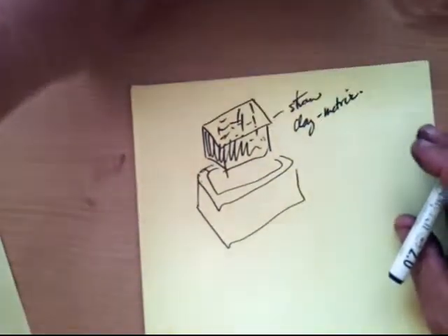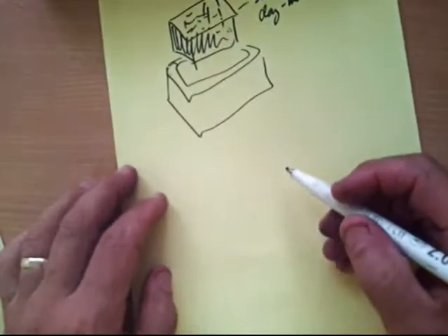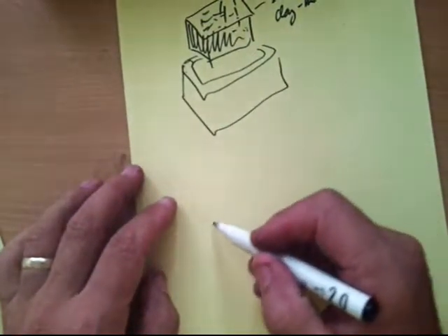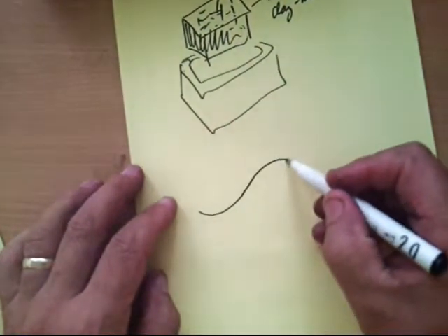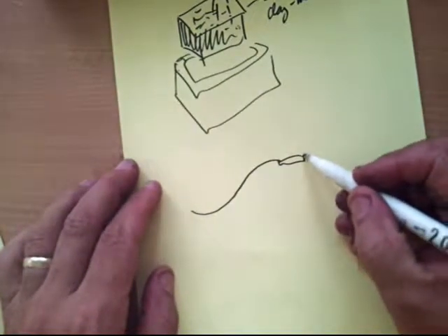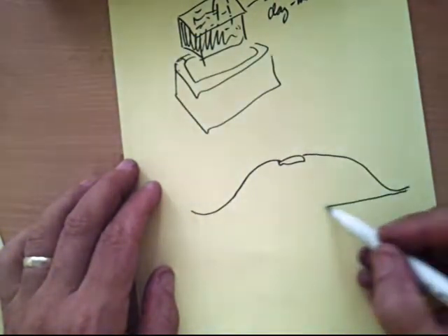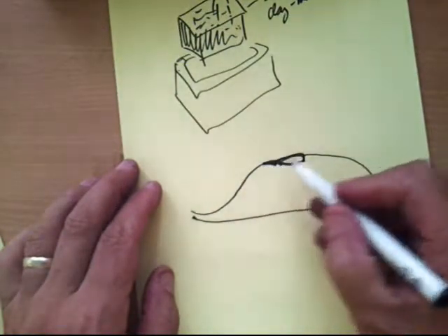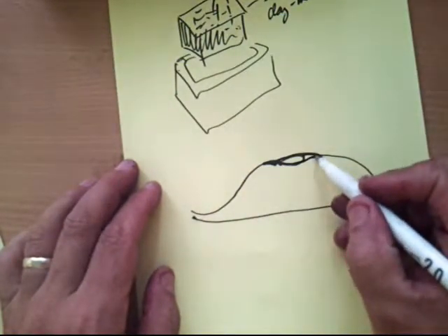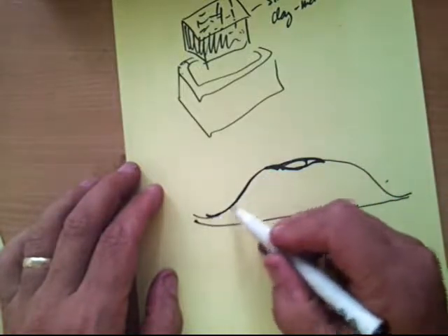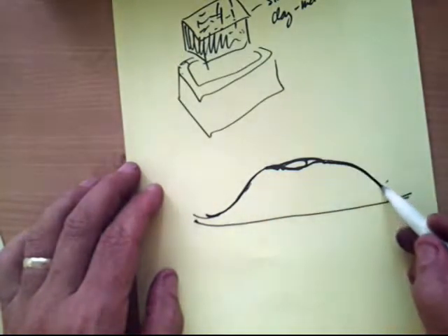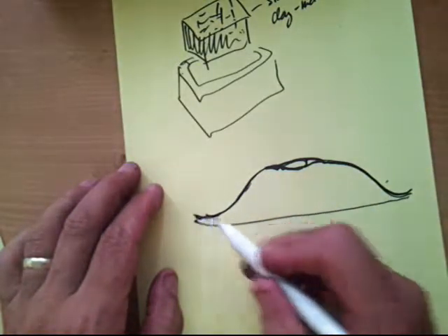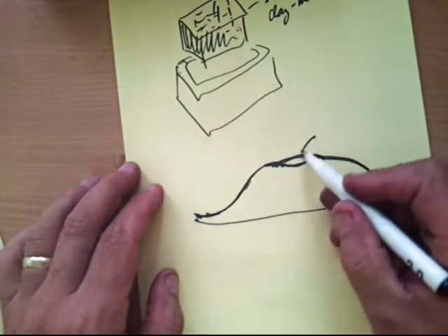Alright, other examples of ancient uses of composite structures would be an ancient bow, especially the recurve bow, which would look a little bit like this when it's strung like that. Oftentimes the handle area over here needed to be very stiff and very hard, whereas the sections of the arm of the bow needed to be flexible and very resilient, able to store lots of strain energy.